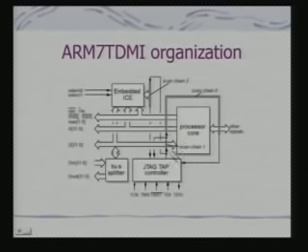So, what I am trying to say is that the JTAG tap controller enables injection of the instruction. An instruction is nothing but a binary bit pattern. The processor core executes that instruction, and the embedded ICE gives you a provision for checking the processor state as the instruction execution takes place.